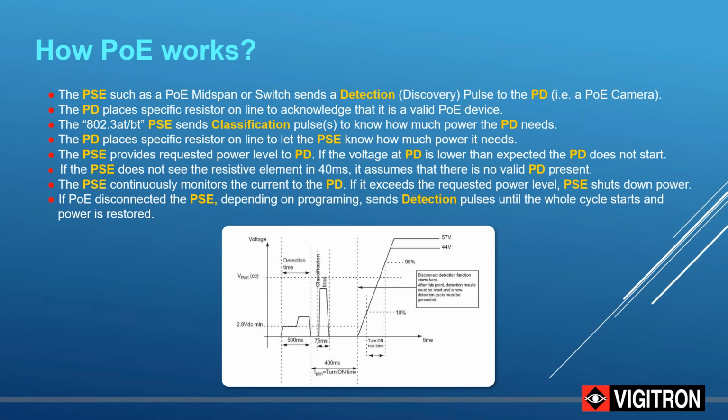Well, resistance within the system affects both. And we know that the longer the cable, the more resistance there is. Well, that applies to extenders and anything that's placed within the system itself, because any object that's placed within the transmission path is going to increase the resistance. So the goal is to basically provide the least amount of obstruction to the transmission of PoE and data within the system itself,